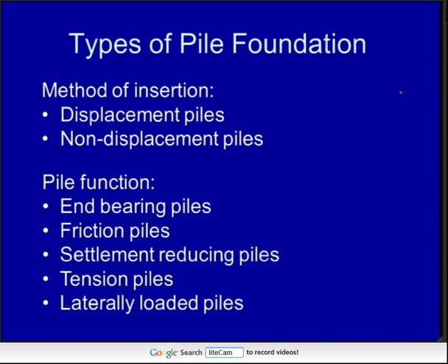piles, you get tension piles. Tension piles are really useful for things like electrical power transmission towers. So you get what are very open gantry type structures, so they are relatively light compared with the wind loading they attract because they're tall, often crossing hillsides. And so if there's wind loading on a tall tower, you can get tension in some of your foundations. And piles, because they have this friction capacity, can resist tension. So a tension pile, the notable thing about it is it has no end-bearing capacity, it's merely a friction pile.